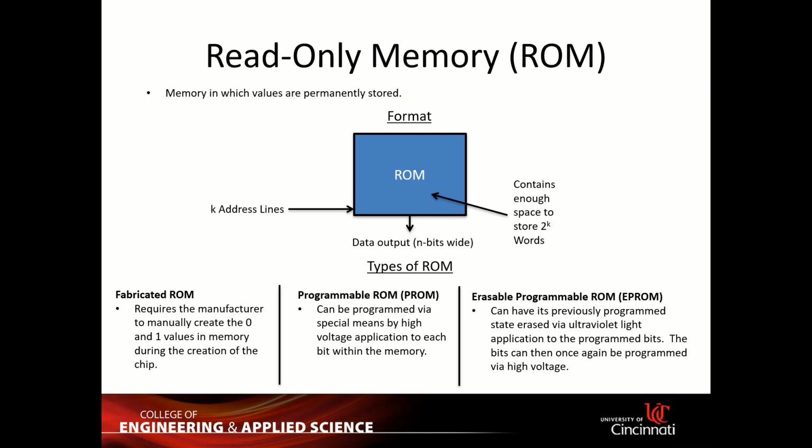So it's a good type of memory. You can keep it there, maybe recycle it, but it's not gonna last forever. So if you work on your Arduino project, as I know, the EEPROMs in Arduino last for probably not over 1,000 cycles. So if you have an application that needs to update your memory a lot, please do not abuse your EEPROM on your Arduino.